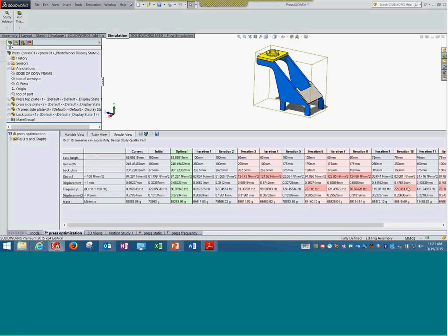And these values, now iteration 1, iteration 2, all these iterations, these values have come automatically based on the algorithm. This is the only difference between design insight and optimization. This is a big difference. In design insight, we are actually specifying what value to be used to give you the results. Or here, the software does it for you and gets a final value which can be optimal.